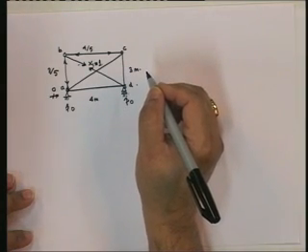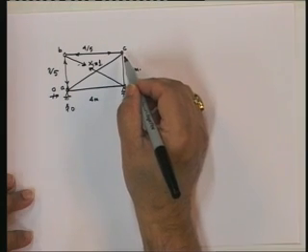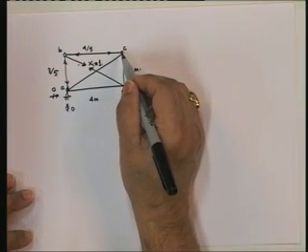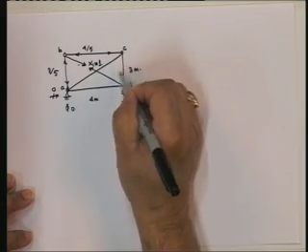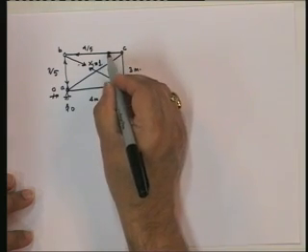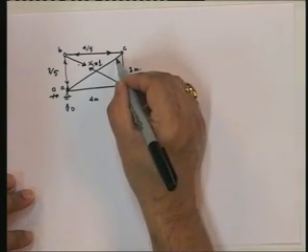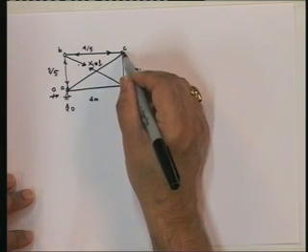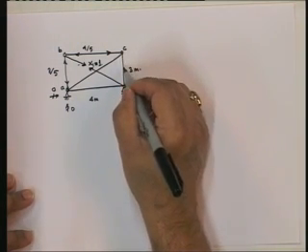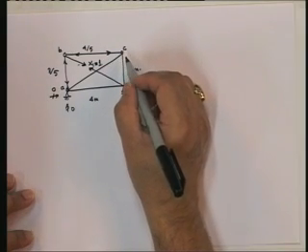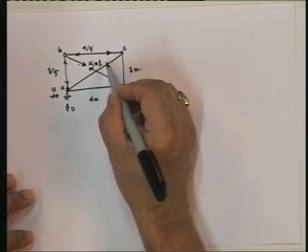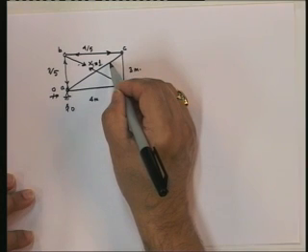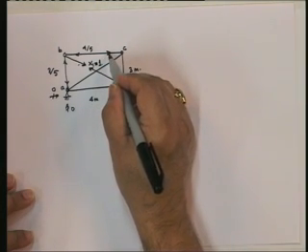And now let's look at the other force. Let's look at this. If you look at this particular situation, okay, what's the force? I know this force. What are the two unknowns? I don't know the force in this member and this member. Well, sigma fx equal to 0 and sigma fy equal to 0 will give me, what will sigma fx equal to 0 give me? That the force in this member, the horizontal component of this, plus this is going to be equal to 0.